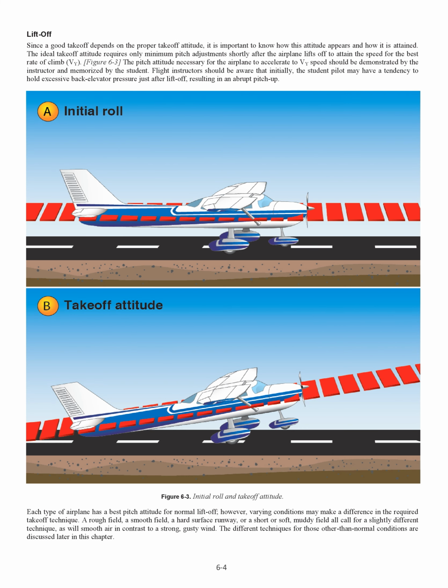Liftoff. Since a good takeoff depends on the proper takeoff attitude, it is important to know how this attitude appears and how it is attained. The ideal takeoff attitude requires only minimum pitch adjustments shortly after the airplane lifts off to attain the speed for the best rate of climb, Vy.